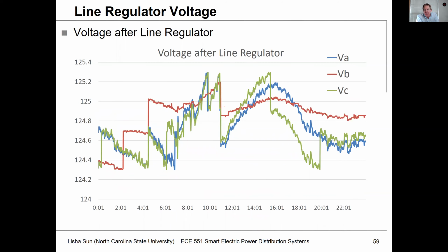And then when we had the regulator operations, I'm showing the voltage in this case, but you can clearly see the impact of the tap changes, where the tap jumps up, jumps up again, gets up to this point, and the tap drops back down again. And when you're modeling the line regulator, you could see these variations and these rapid fluctuations in voltage.